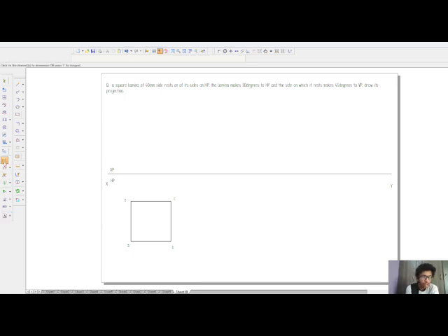Now, using the smart dimension, we will measure the length of the side. Now, using a normal line, we will draw projectors from the points down to the XY line. Now, the two projectors which we got from the surface lamina will be joined using a visible line on the XY line.